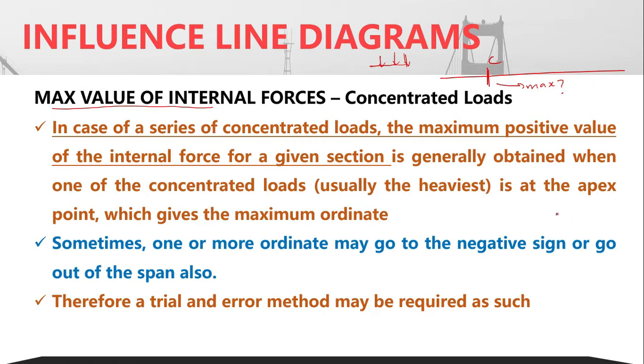For example, if I have a simply supported beam like this, and I want to find the value of bending moment, I draw the ILD, which will be like this. In order to get the maximum value of bending moment, if these are P1, P2, P3, etc., I place the maximum of these loads directly on top of the maximum ordinate.